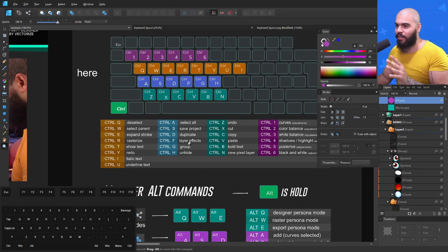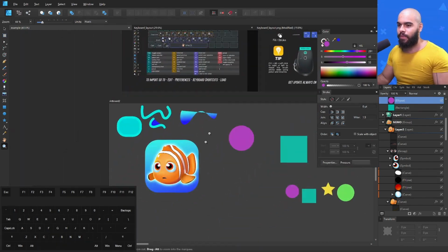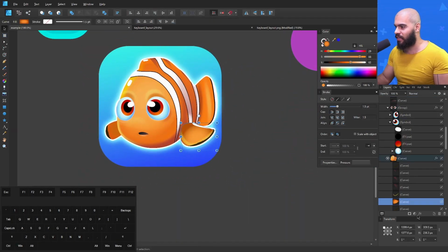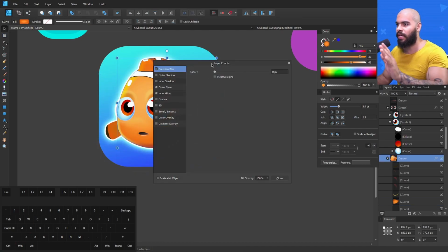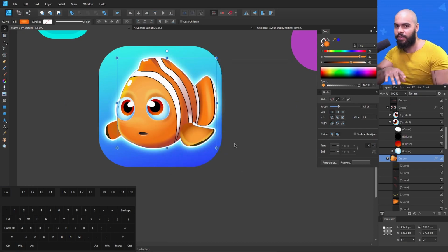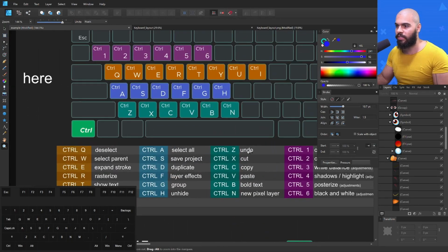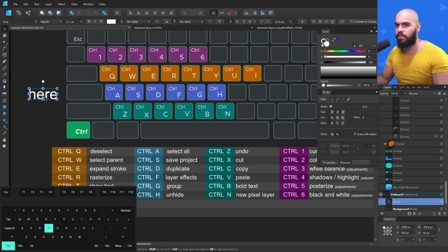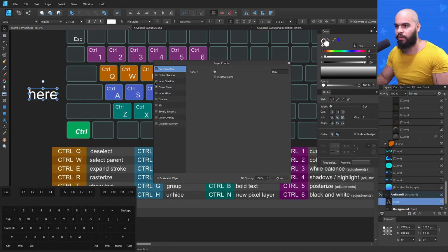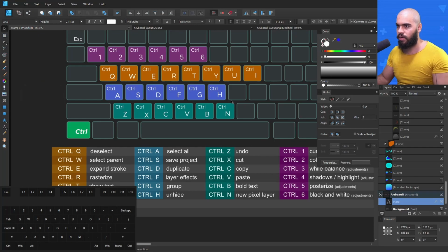Ctrl F, it is very good. It's very nice. What is it? The layer effects. Instead of clicking here below, you can simply select the subject. Ctrl F is gonna enable this panel, and then you can click here. There you go. Simple like that, my friend. Ctrl F is control of layer effects. Think like that. Layer effects enable only what is selected, right? Select this font, Ctrl F, and then if you apply Gaussian blur here, it's gonna apply Gaussian blur over here. Clear, right?